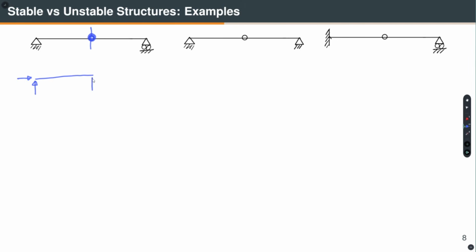Here at the hinge, I can draw like this, okay, 2 unknown reactions. And then equal and opposite is acting here, and then you have that. Okay. So, how many free bodies we have? We have one free body here, we have another free body here, right.